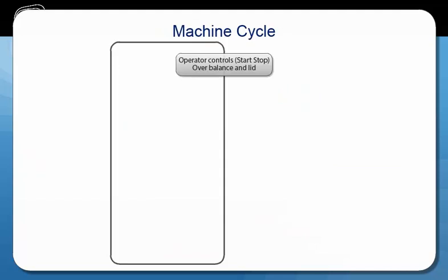In the main program, we have the start-stop controls, plus the calls to the subroutines. When the start button is pressed, the variable cycle is turned on. It will stay on until the machine completes or the stop button is pushed. The fill subroutine is called. We want to run the subroutine until the machine is full, and then we don't want the fill to have an effect until the machine is restarted.